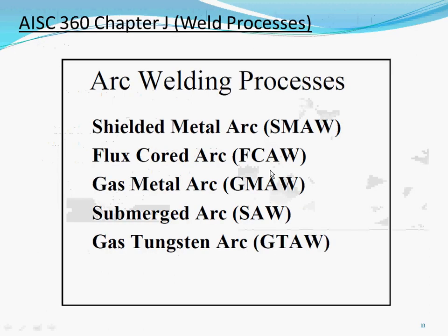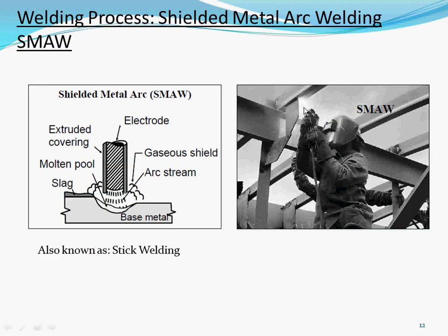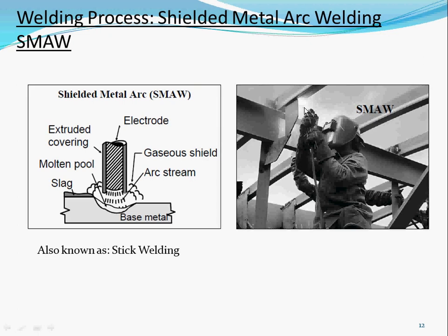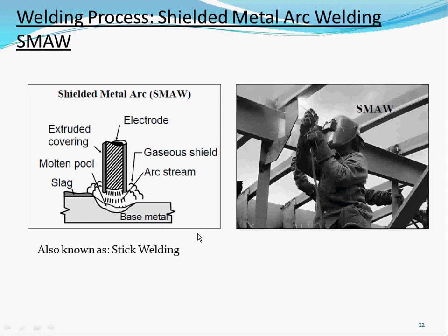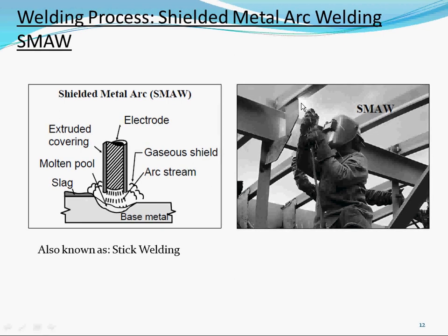I think this one is probably the most familiar to people. You actually have a stick. You stick it in, and then you can weld whatever you want. It's very portable, very easy to use. The equipment is cheap, and you see a lot of countries start welding with this first. However, you do have what they call slag covering it, that you need to remove after each pass. What that means is you don't want to get that in your weld pool.